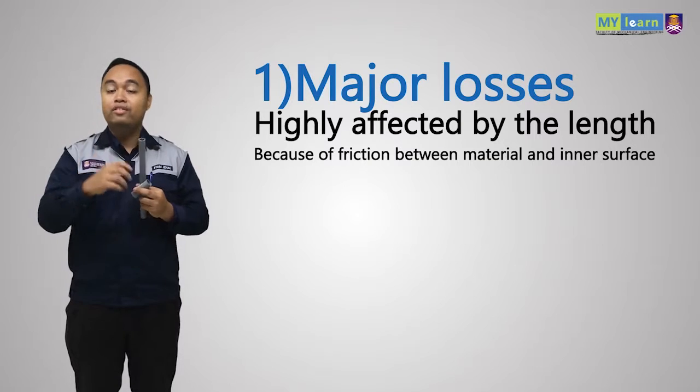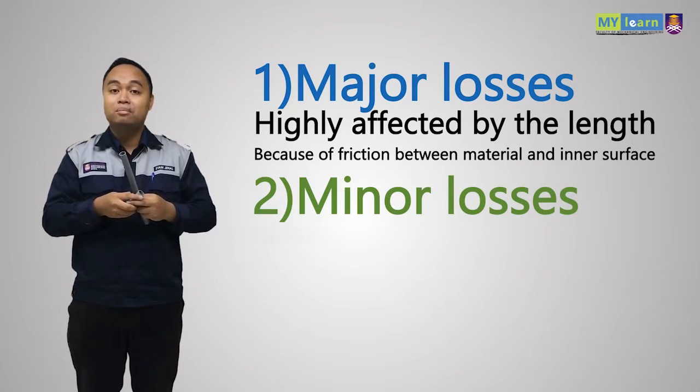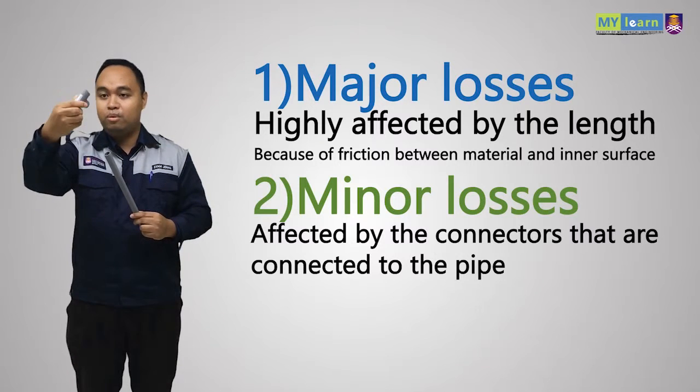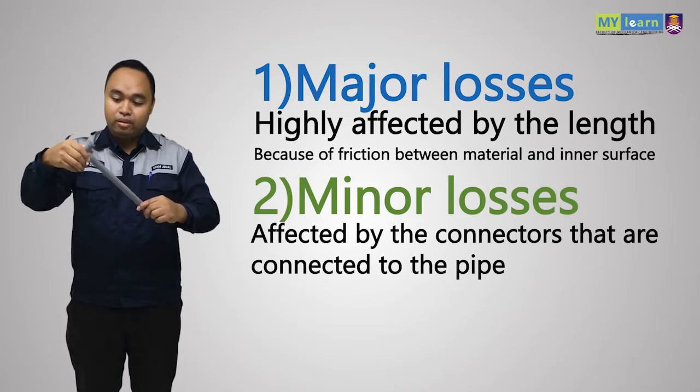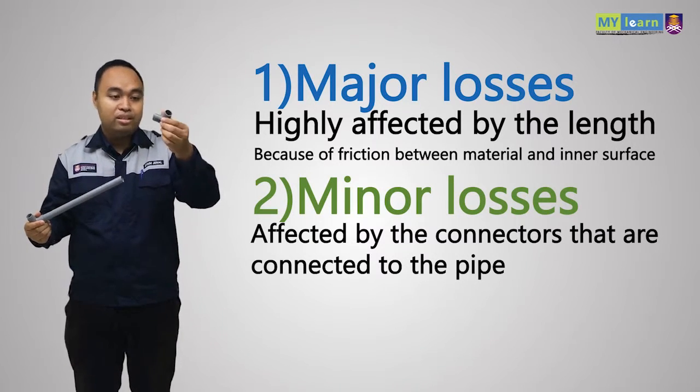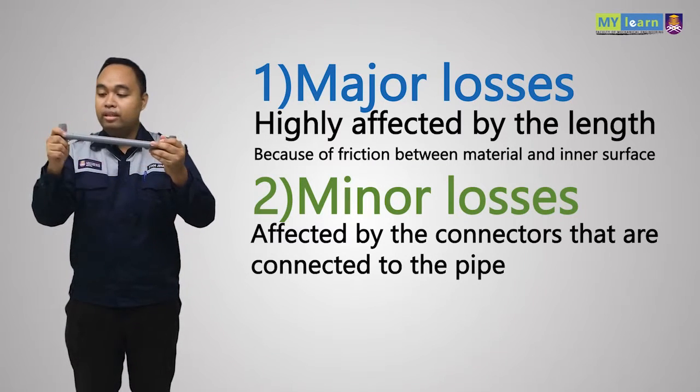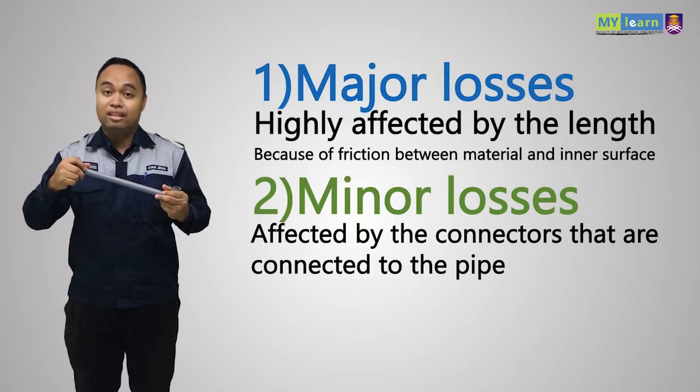However, minor losses are affected by the connectors that we are using inside the pipe. For example, I have a T shape over here, and then a 90-degree bend over here. These two connectors will provide some minor losses inside the system.